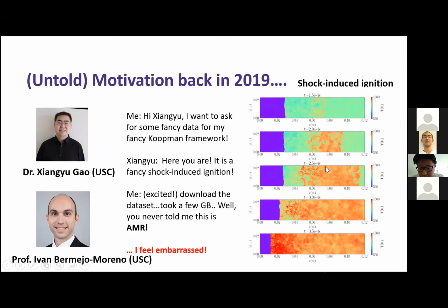As you can see, there are so many fine vortices over there. So it is best to use an adaptive method if you can find one that is appropriate and fits well for adaptive mesh refinement, rather than using POD or CNN methods, because POD requires a fixed mesh at all times.